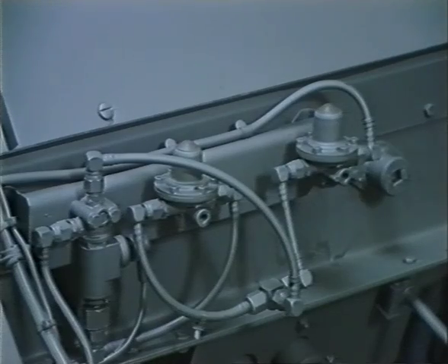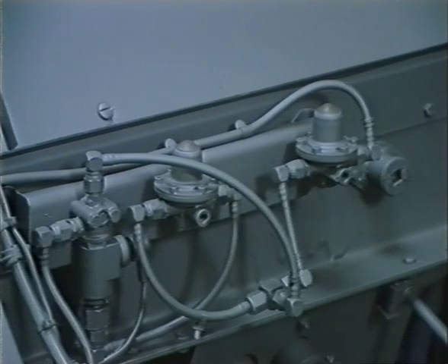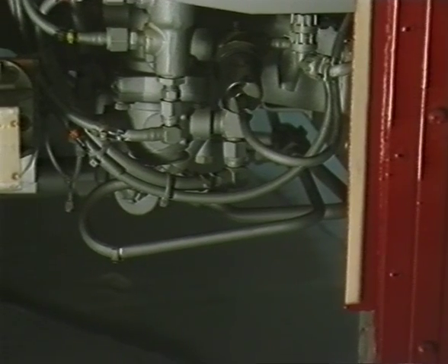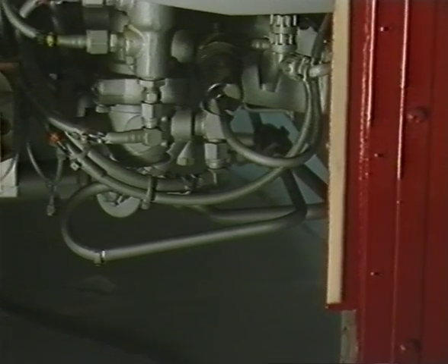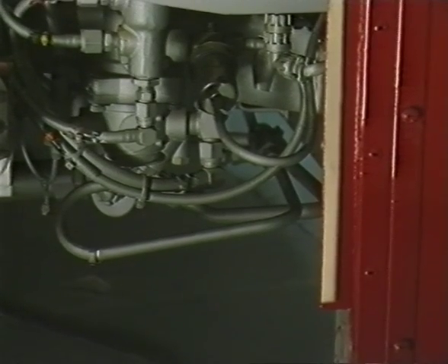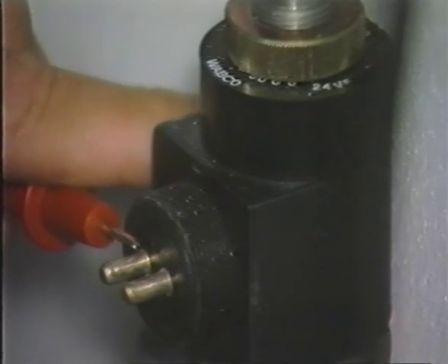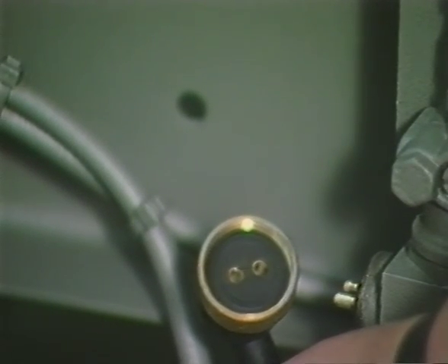In this fault area, first inspect the MV4 solenoid and see if it clicks when the foot brake is applied. If it does, check the air pressure supply to the MV4 solenoid, which should be 3 bar. If not, check and adjust the limiting valve. The second stage retarder is triggered by an air pressure switch in the rear brake output line. Therefore, to establish if it's functioning, apply the foot brake and carry out a continuity test across the switch terminals. Next, carry out a resistance check on the MV4 solenoid and a cable check from the pressure switch to the solenoid. If no fault is found, the suspect area is the EP section of the MV4 solenoid.